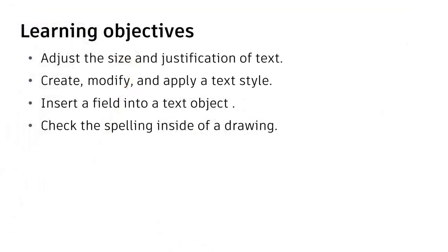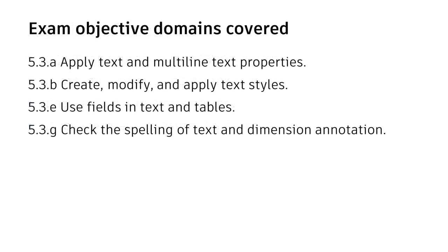We're going to be looking at how to create, modify, and apply text styles. Text styles are used to manage and automate almost every aspect of your text objects. Text styles allow you to maintain consistency in your drawing annotations and to organize your text.